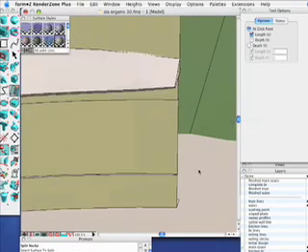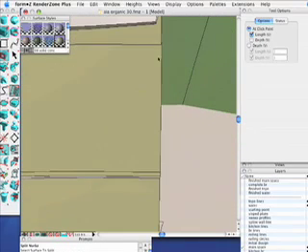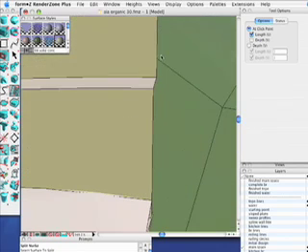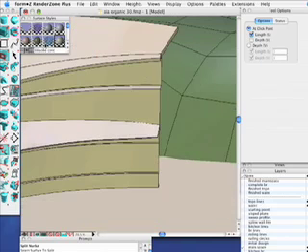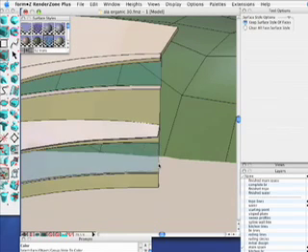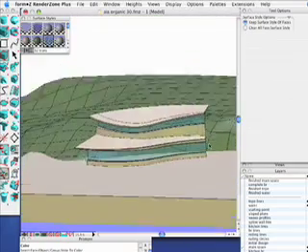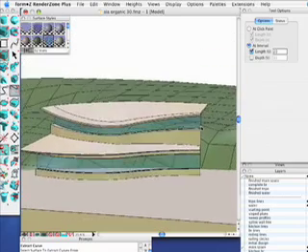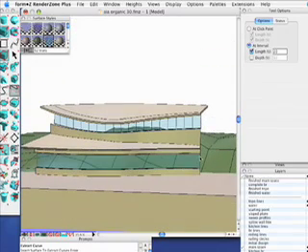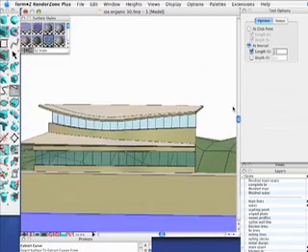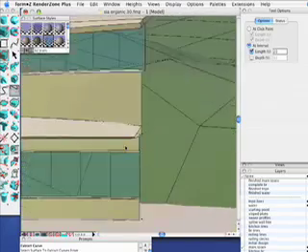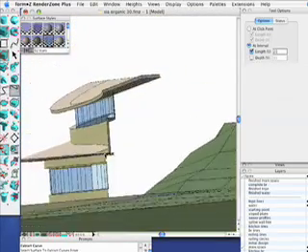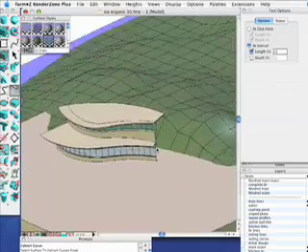Now you notice it's all kind of monotone. Since this is NURBS, I'll use a NURBS split tool to cut these shapes into multiple pieces, and then I can color these new pieces a glass-like color to create some windows in this front facade. How about some mullions? Well, NURBS have a tool called Extract Curve, and I've set an option to extract 20 curves from the surface, and if I pan around here to the side, you'll notice that those curves match that surface exactly.